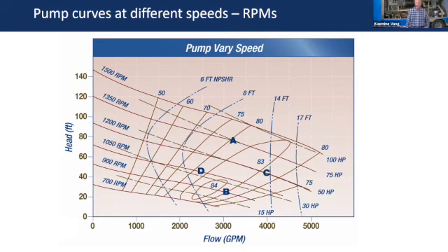Yeah, actually, maybe not the limitation of the VFD so much, it's a limitation on your pump motor. A lot of times, I didn't even mention this because we didn't have a lot of time today, but you may have to put different windings in your pump motor. Your old motor might not be set up for it because you may run hotter, especially if you run that pump slower. You remember that as the pump is rotating, that motor is pulling in air through the vents, through the fins or whatever they're called there, and it's cooling itself. And when you start slowing it down, it doesn't cool itself as well.